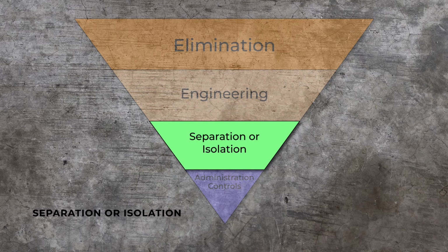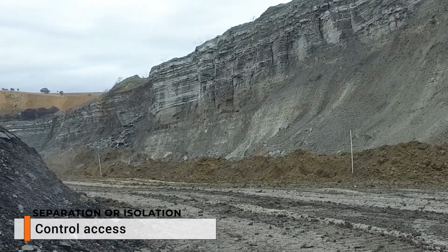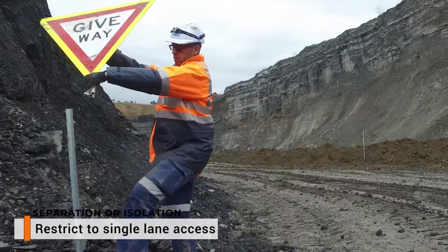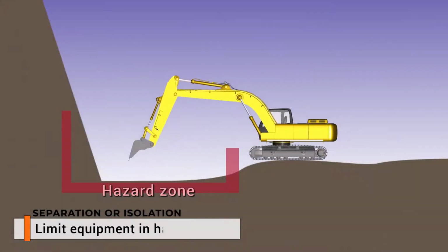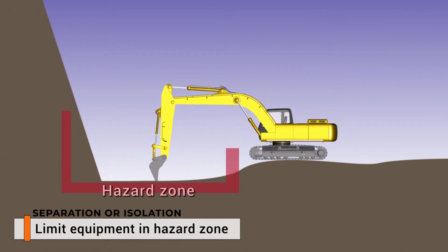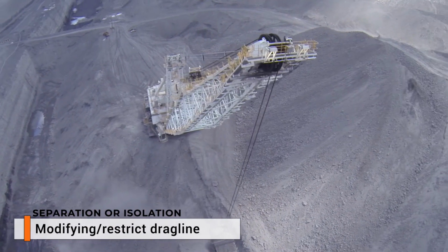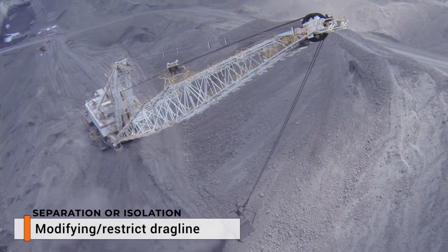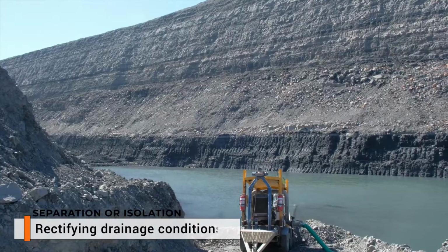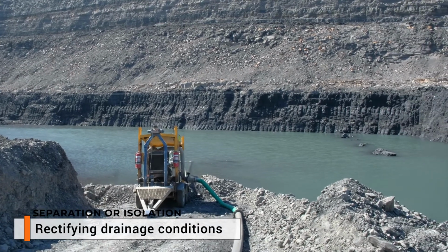Separation or isolation controls. Controlling access at the crest or toe of the identified hazard by installing hard barriers. Restricting to single lane access past the hazard. Limiting equipment used in the hazard zone, such as allowing the excavator arm and bucket only inside the hazard zone, or modifying or restricting the dragline dig sequence to minimise exposure to the hazard. Regrading or re-establishing tip heads. Rectifying drainage conditions, including installing pumps and grading slopes away from the crest into a sump.